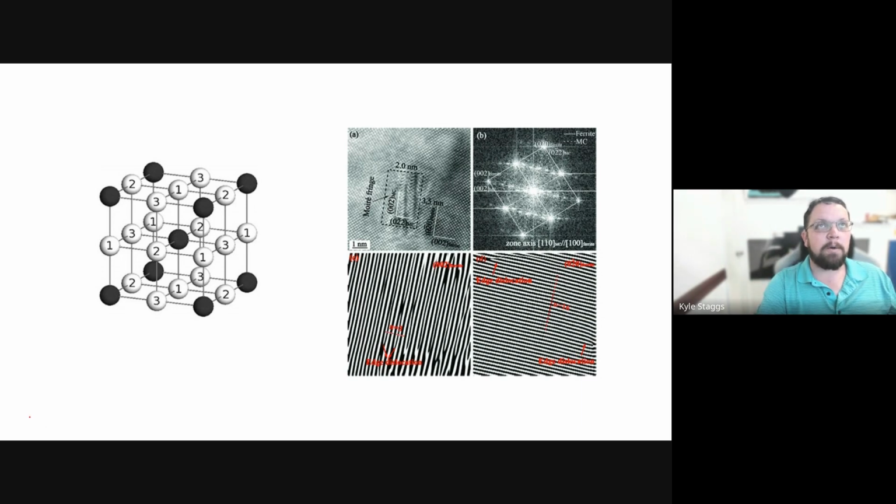At the top here, what we've got is a couple images of the actual carbide. So they're showing where the ferrite boundary is, and they show a couple of different lattice parameters here that line up. So sometimes you'll have 2, 3, or 4 different lattices that will show up in a spectrum on a material just because of the way that different specific grains are oriented and things like that. So there's a boundary that they're looking at specifically here with a couple specific planes.